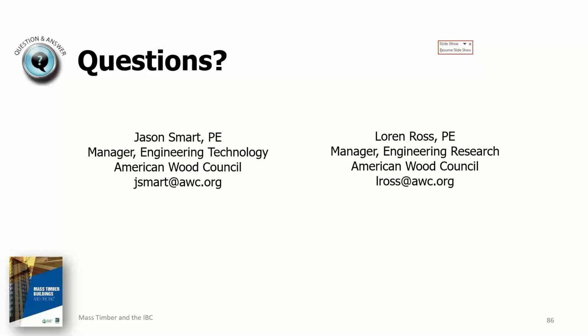We were talking about sound transmission and how increasing the mass of an assembly can benefit the acoustic performance. So we often do that with mass timber assemblies by adding a layer of gypcrete or lightweight concrete topping on top of the floor slab. Someone had a question: can this affect the vibration performance of the floor? And are there any vibration controls or requirements that are out there that we could point folks to? Yes, there are resources available.